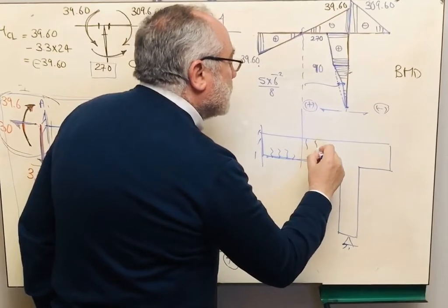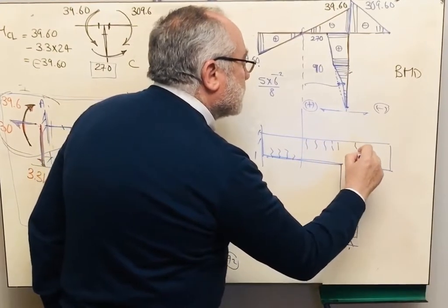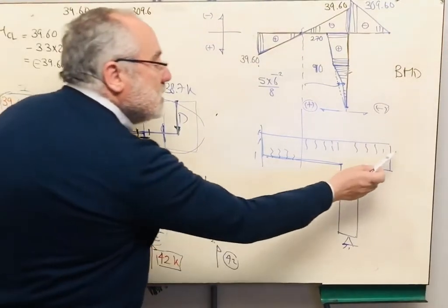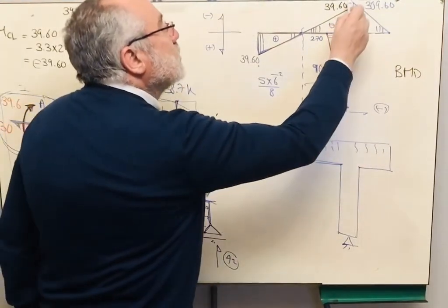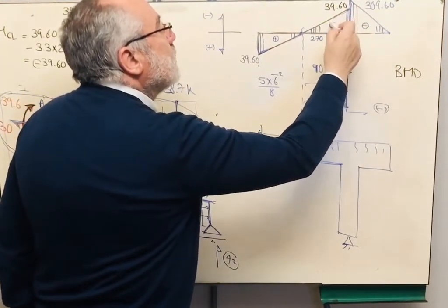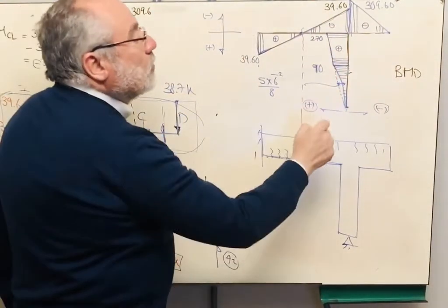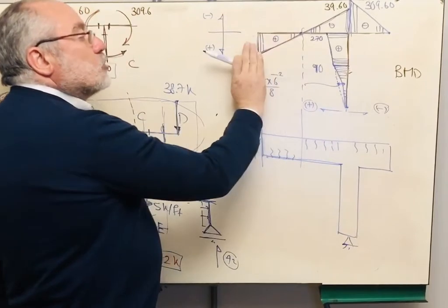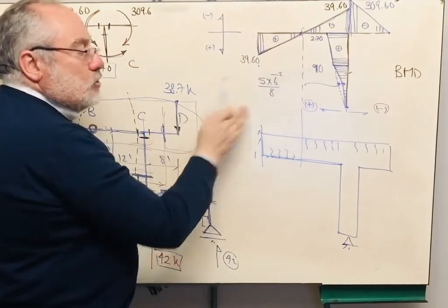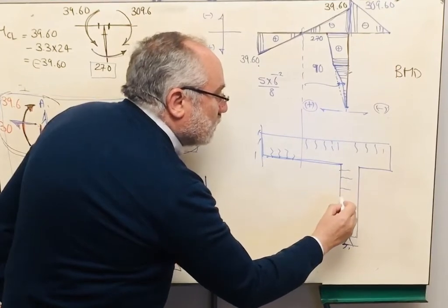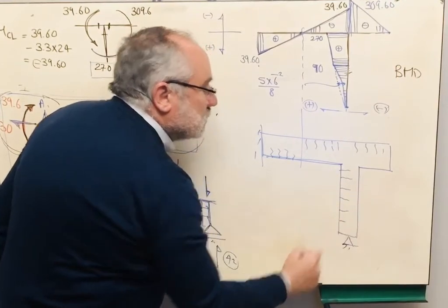So the cracks will appear on this side. Right? Maybe the cracks here is severe because the bending moment is 309 compared to 39.6. Now, how about the column? The column, the bending moment is drawn on the left, on the near side when you are standing under the frame, which means that the cracks will appear on this side.